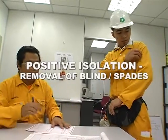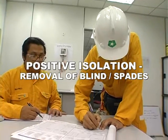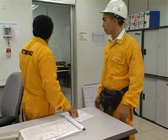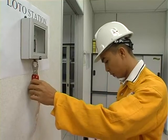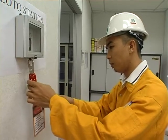For positive isolation at the field, AA must issue separate PTW to remove the blind or spade. Before removal of blind or spades, RA must place his department lock and personal brown tag at the lockout box.